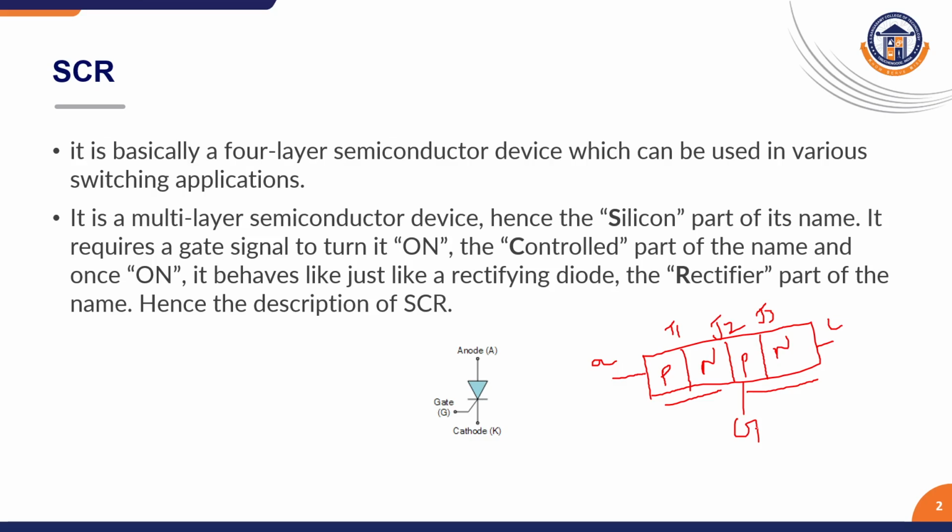It has very low resistance in forward conduction and very high resistance in the reverse direction, and can be controlled. An SCR blocks the current flow from anode to cathode until it is triggered into conduction by a proper gate signal between gate and cathode terminal.